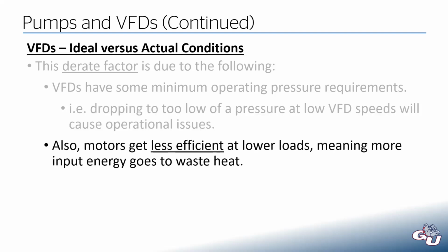Another reason is motors get less efficient at lower loads. If you think back to when we first talked about motors, I said motors like to be loaded. And if we are reducing the pump or fan speed, we are effectively deloading the motor.